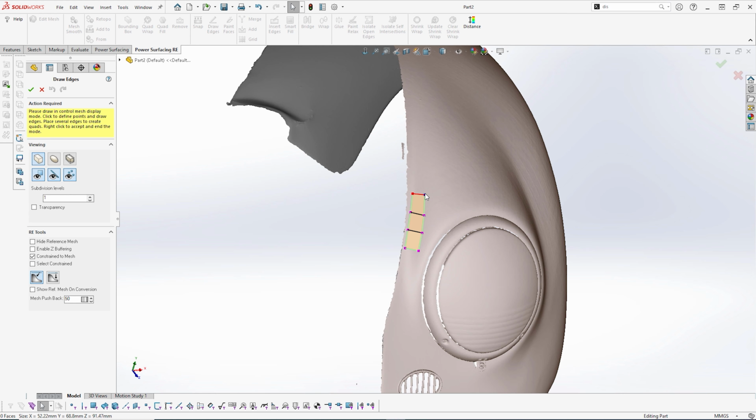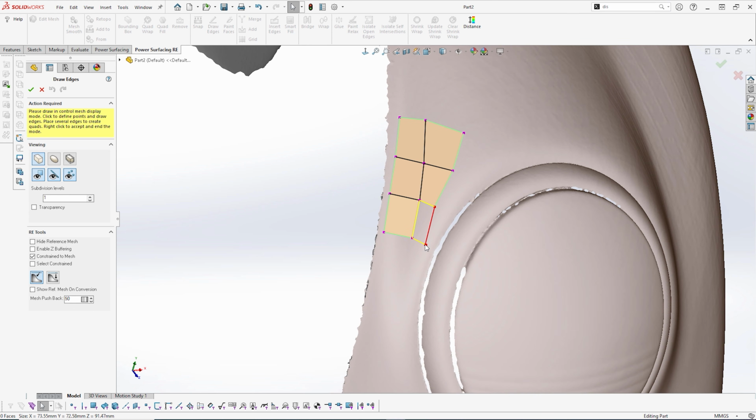Now what I'm doing here is simply drawing the edges, drawing the faces, drawing the sub-D onto the mesh. Notice how I'm trying to do relatively smallish faces. This is just because it helps me capture more detail. You'll see in a second that if there's a much larger section, like the rest of the panel, I'm going to try using much larger faces. This is mainly for speed purposes, makes me work faster, but also because there's less detail to capture, I don't necessarily need small faces in order for it to work.